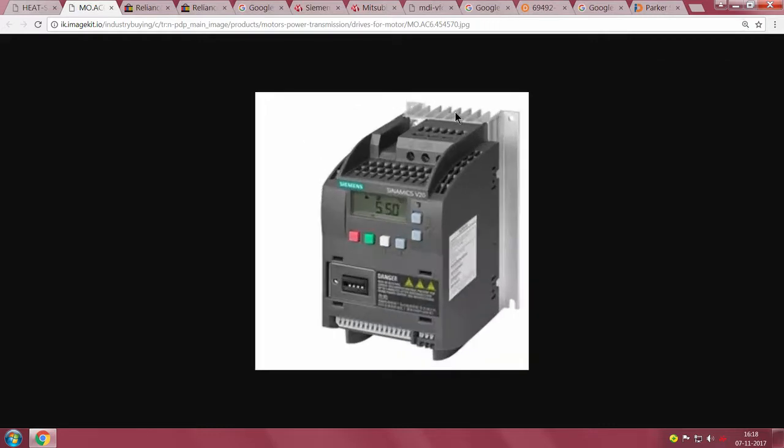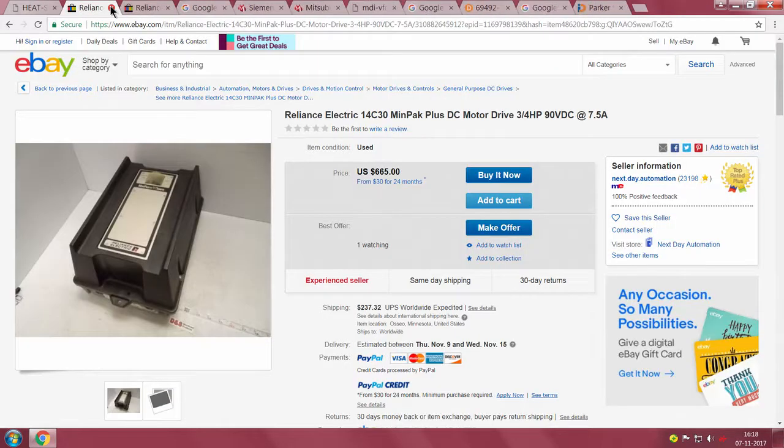You will notice something very clear here. Heat sinks are not black anymore. Long ago we used to think they are required to be black. Obviously, for any aluminum, especially the one in convection, the anodic layer has more to do with protection and electrical insulation and so on. So, in this case the mounting holes and this whole thing has been integrated into that, and this whole shell sits directly on top of it.